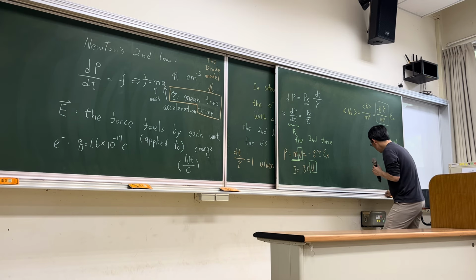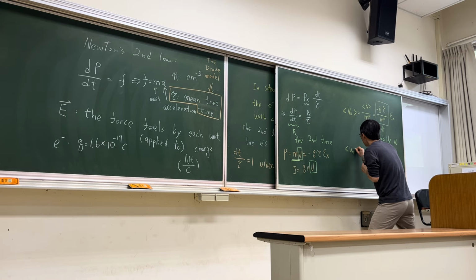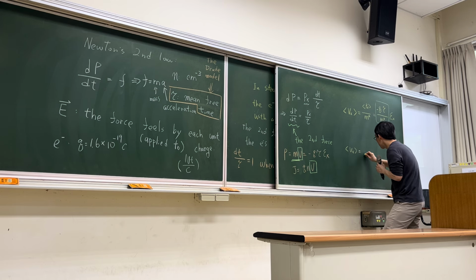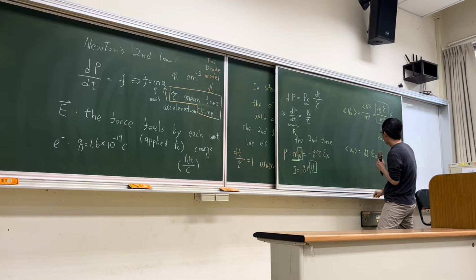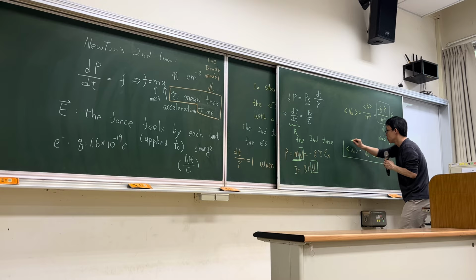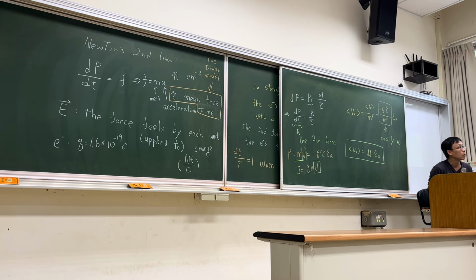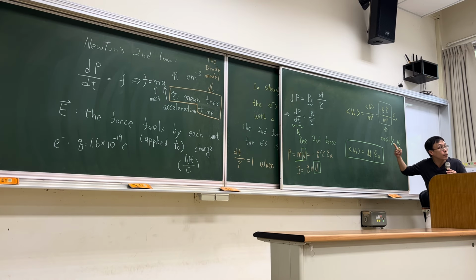So in summary, velocity is proportional to the electrical field with the constant of mobility. This is a very important formula, because it tells you how fast a free electron can run under the influence of an electric field: it is determined by mobility. Because this electric field can be a constant. It is only determined by the voltage applied to the device, right? For example.